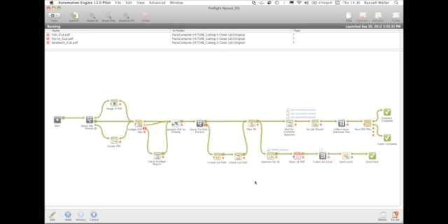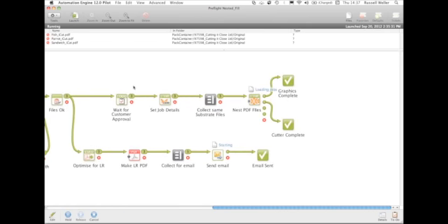So this is where the intelligence of the job management system comes in. So I know that these 10 files over here need to be fused and laid out with these 10 files over here. So let's accept these again so you can see the stages it's going through from a workflow concept. I accept them. It sets the parameters, in this instance the quantity. It collects all of the files together, and then it sends them down to, and if I zoom in to see what's going on here, the actual nesting. So I'm actually asking all of the systems to do this for me. In the meantime, my email is being sent, but likewise here as well, it's actually nesting those files. It's going to create a nested layout for me, and it's also going to create the relevant cutting file.